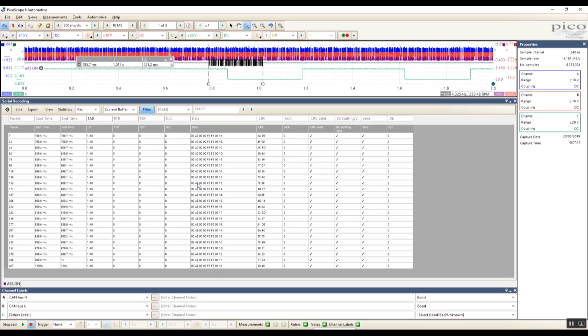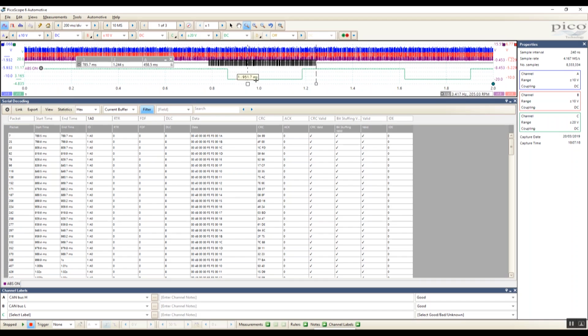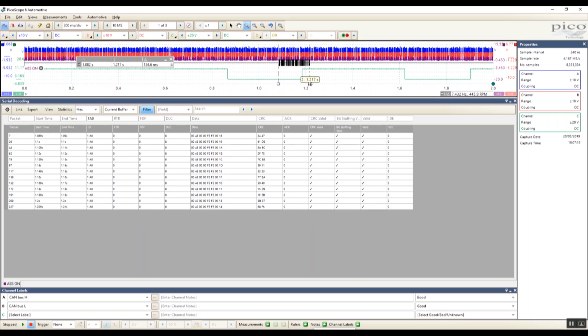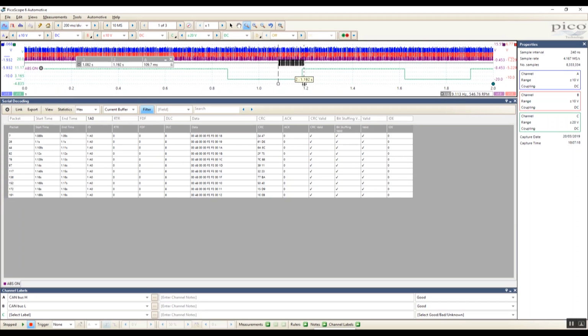Yeah, 4.0 to 4.8. That's at the point the brake pedal goes on. It remains on. Let's pull this out here to there. So we go from 4.8, brake pedal on, to 4.0. And let's see if we can really narrow this down. Yeah, 4.0 is brake pedal off. 4.8. So we see how the brake pedal has gone off at this point when we're measuring at the brake pedal switch at the master cylinder.